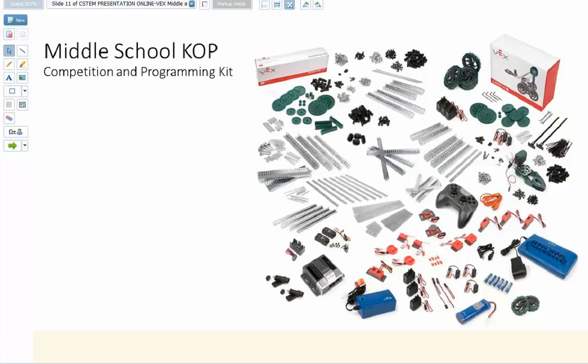So go in there. All the framework is all the silver I-beams and H-beams that you have here in different types of sheets of this metal. It allows you to create the bases and everything you're going to be creating with the actual VEXnet, all the different connectors and shafts. These little shafts here are very important. These shafts typically help you create the extensions for the motor, so you can add sprockets. There's some more here. These are extensions you can cut and use as motor shafts as well, for wheels. You can make them for wheels, so the motor and then the wheel gets attached to this part, and then you can use one of these little couplers to keep the wheel in place.